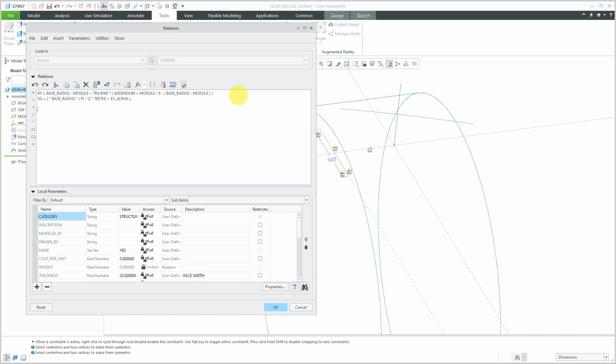That's good. Now we're going to use something interesting. We're going to control the size of that dimension using an if-then-else equation. And so we're going to do that if ry, that local variable that we calculated, is less than our base radius, then we're going to assign to the dimension. I like to use some spaces in here. Here's our SD3 dimension, the width of that. SD3 is going to be equal to that ry that we created times SG, the other local variable, divided by our base radius.